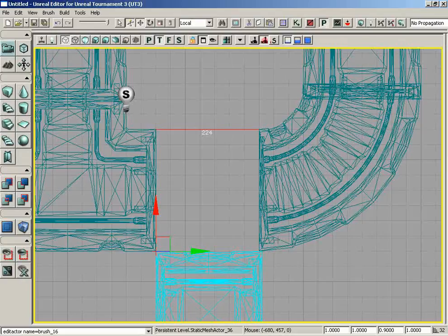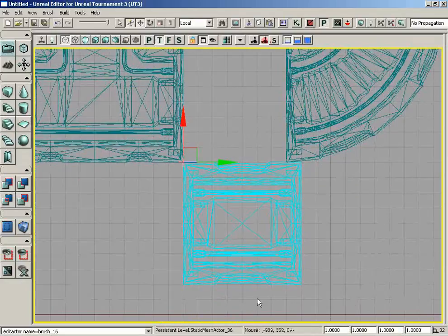And let's also measure the mesh itself. If you don't mind, set the draw scale back to 1. Sure thing. So we get an idea of what was the original size of this mesh. So from one end of it to the next, we might need to actually... no, it looks like it's still on grid snap settings. So, boom, it goes to 256. So there's our problem. We're trying to fit a mesh of size 256 into a space of size 224.